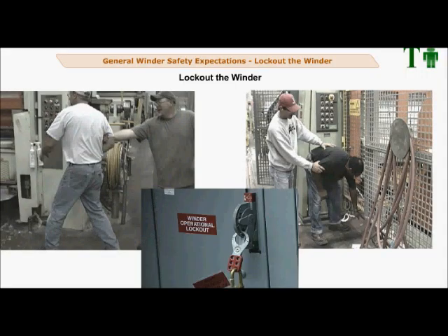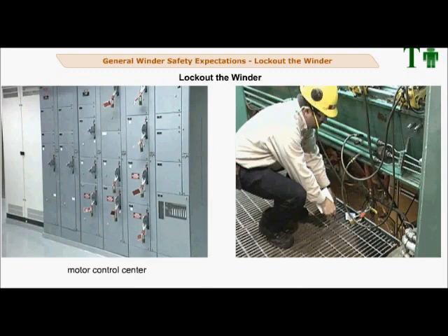Lock out the winder. If you need to place your body or body parts into the winder other than your normal safe practices, you must lock out the winder. Lockout, tagout does not only mean the winder drives on the winder. There are many other areas of the winder that need a form of lockout during operation.